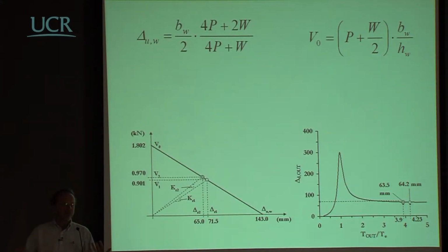If the two displacements are quite different, you have to iterate and find the displacement that will give you the proper period of vibration of the out-of-plane response, to have that demand coming from the in-plane action on the structure. And this is it for what concerns the masonry structure.